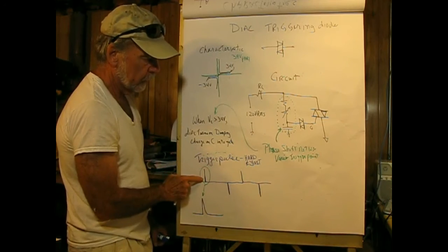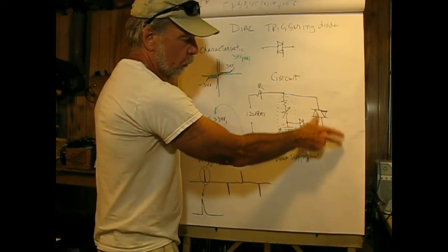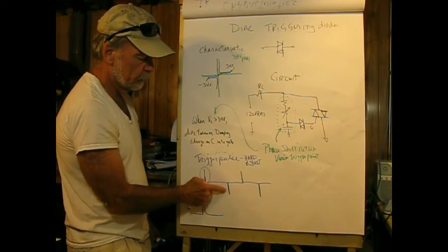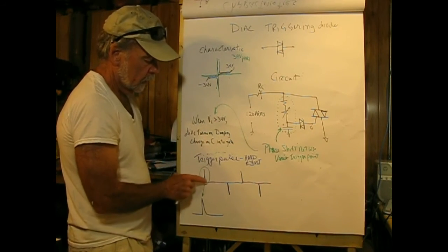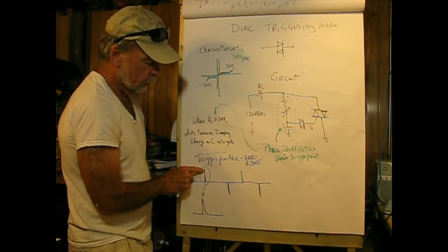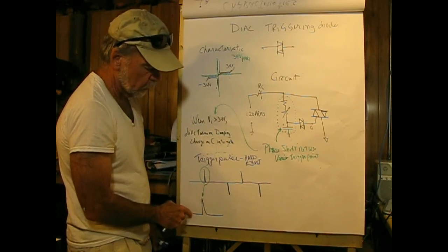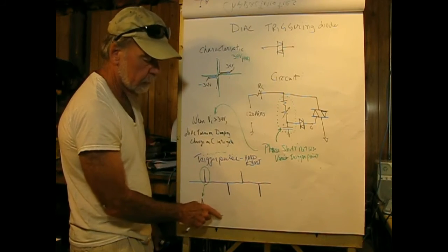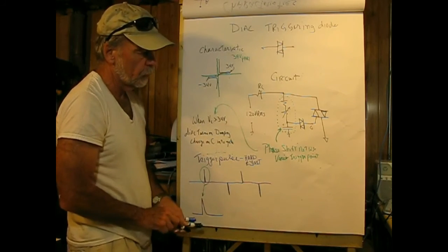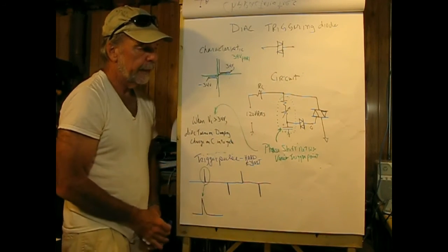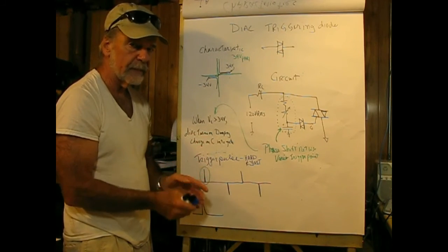And this would be if we elected to examine this. We can do this in the lab by putting a little resistor here and omitting this part, because we would see the pulses be very, very quick, up to the voltage across whatever resistor we put in the circuit, and very, very fast. If we expanded that out, what we would see would be a typical exponential decay. So the purpose of the trigger diode is to trigger SCRs and/or triacs very quickly and with a lot of gate current, so they turn on immediately.